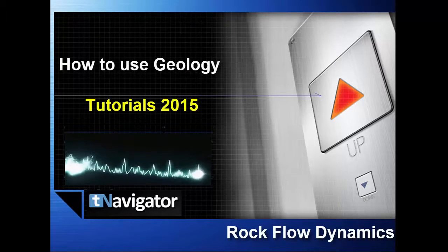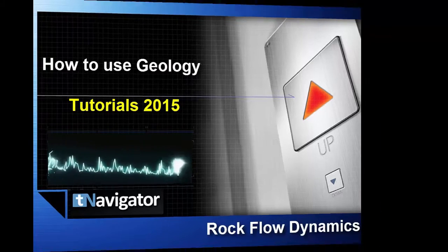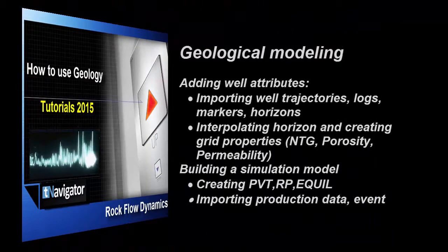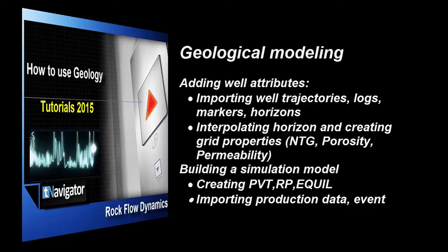Geology modeling allows you to understand, assess, and predict your reservoir by incorporating all available data. T-Navigator geology modeling allows you to create a realistic geological model. In this tutorial, you'll know how to import trajectories, logs, well markers, horizons. Then, how to interpolate horizons and create grid properties using well log data.